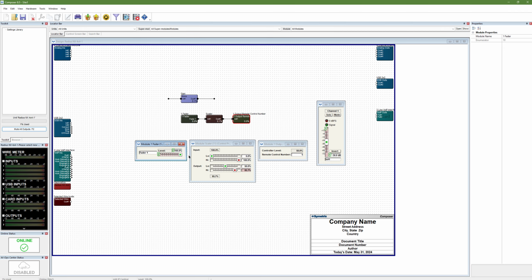The control fader is what would be set up for the end user to control in the programming. It in turn controls the gain fader, where the actual audio is passing through. Be aware that the representation will be in percentage, not dB. While the dB level box from the gain module can be set up to remote control, the third-party controllers should be consulted about how it will represent this value.